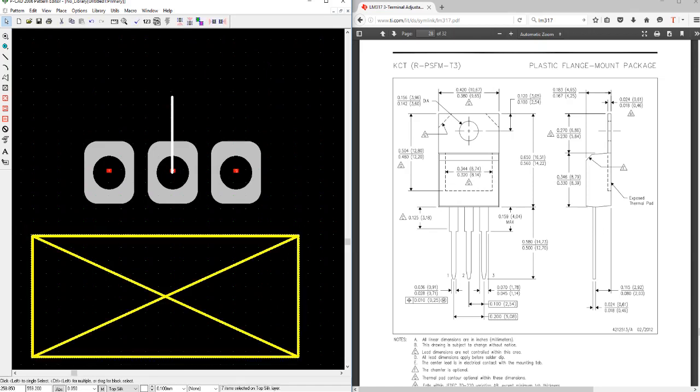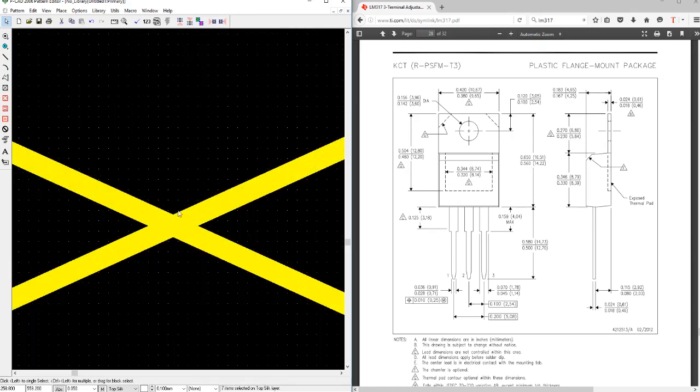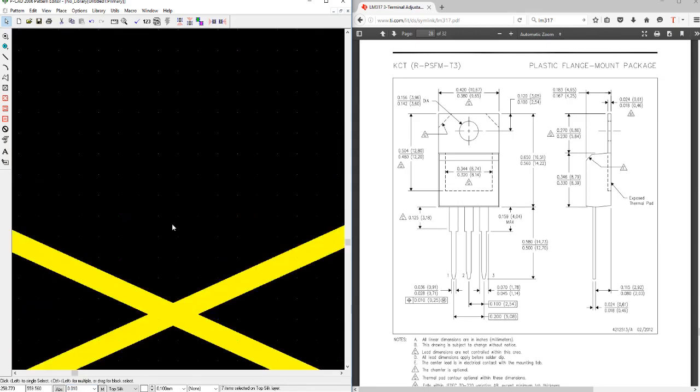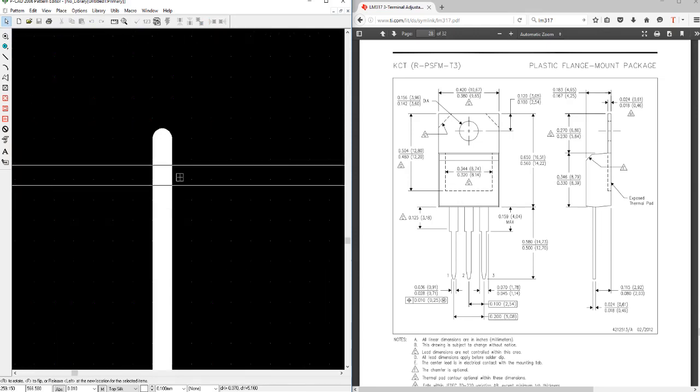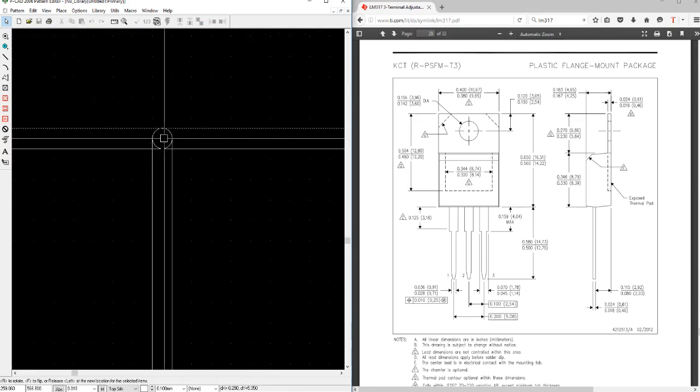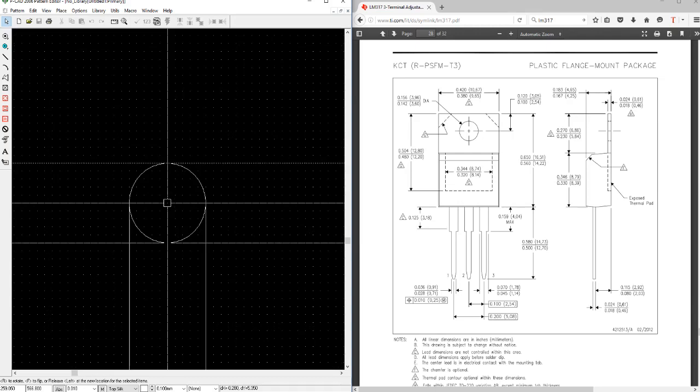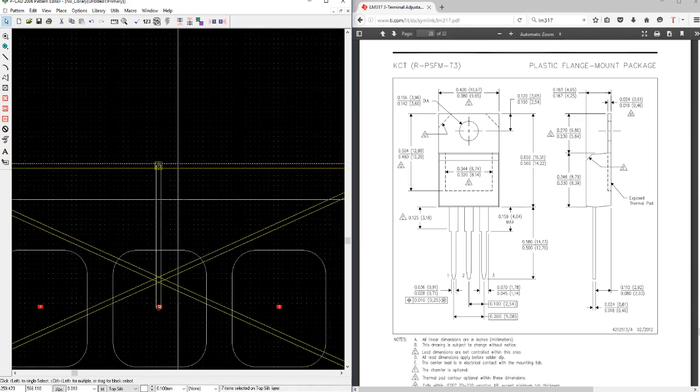So we select this block, we go to the center. I'm going to make my grid slightly smaller, because otherwise I'm going to run into issues. And then I go down to the middle of the line. I can press X to cycle through my cursor styles. I grab it. So there I've got it on the center line. I can press Q to go to draft mode. I go down and I put it right there in the middle.